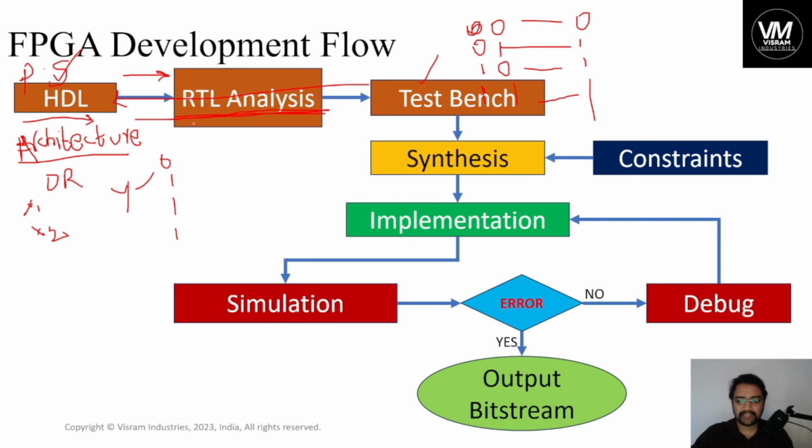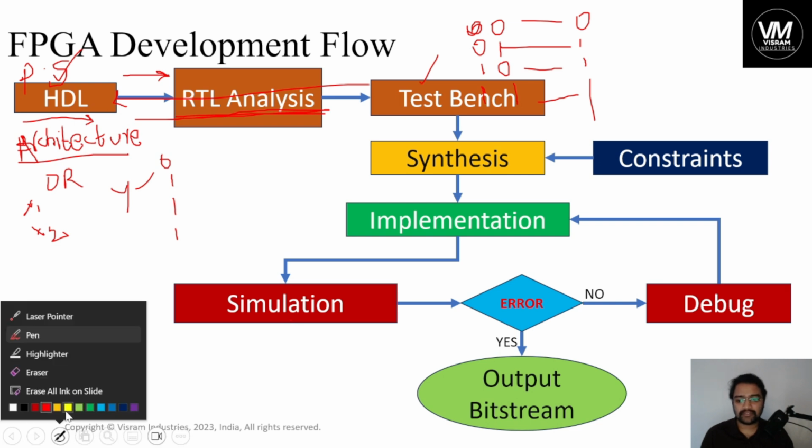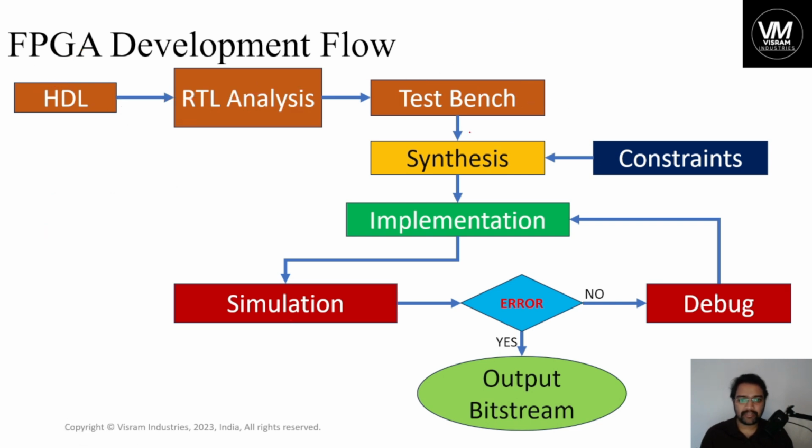So please understand this is the verification process in the HDL. And then after the test bench you can run the synthesis successfully. By synthesis you can also see some simulation with the timing simulation charts, as we have seen in the previous lectures. And then for the synthesis you will be adding a constraints file, and in this you can add the constraints according to your design.